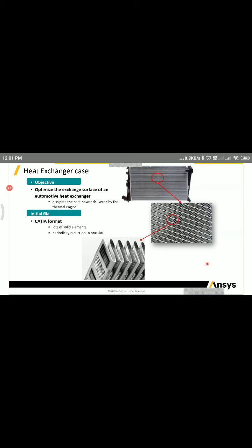So similarly, this is a CFD problem. We might need to see whether we have to consider this as a complete model. What if we try to reduce the size? What if we can see if there is any symmetry available? What if we have some periodicity in geometry, right? So we can take help of this. Instead of modeling 360 degrees, why can't I model just 45 degrees? If it is linearly periodic, why can't I model just one section that completely represents all the things,